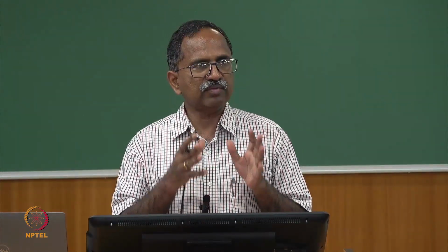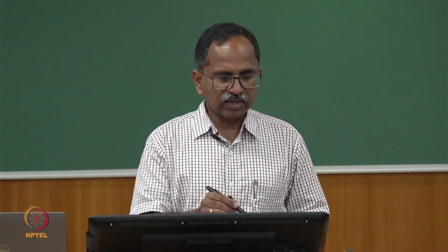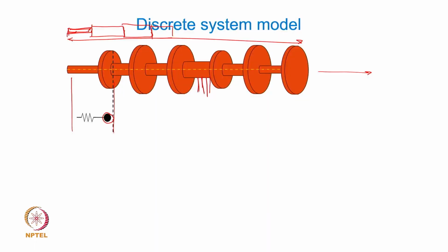You treat each segment separately, and the vibration will happen only if you have a mass and a stiffness. That means there has to be an element for storing strain energy and an element for the kinetic energy. So each segment will have a lumped inertia element and an element to store the strain energy. You have a stiffness and a mass or inertia element, and together they constitute a segment. And when you couple all such segments one after the other, you get the original system. That's the philosophy here.